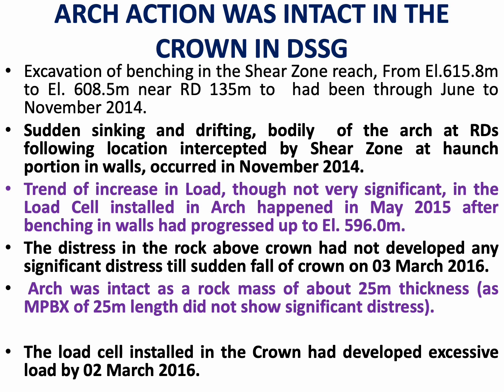So the important observation is that within the thickness of around 25 meter, which is equal to the length of the MPBX, it can be observed that at least to a depth of 25 meter into the rock from the excavated profile, there were no distresses seen in the crown.